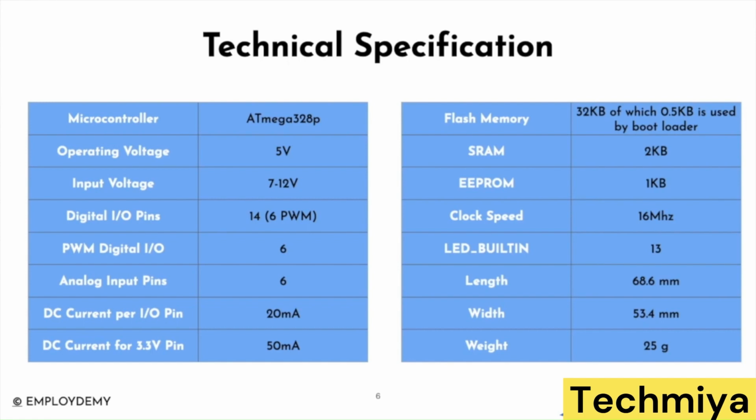What is the size of memory? Whatever program you write gets flashed in memory, right? It gets downloaded and burned in the memory. So what is the max size? There is a max size of 32 KB, so your program can be at max 32 KB in size. Out of this 32 KB, 0.5 KB is used for the bootloader, that is for your boot ups.